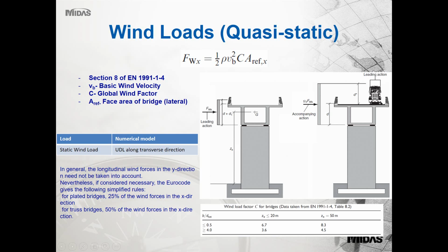Okay, after calculating these forces, wind transverse, vertical and longitudinal, they are then combined. So we generally combine transverse with 50% of longitudinal, or maybe 50% longitudinal plus 50% vertical plus transverse full. Because it's highly unlikely that all three of them will be acting simultaneously.